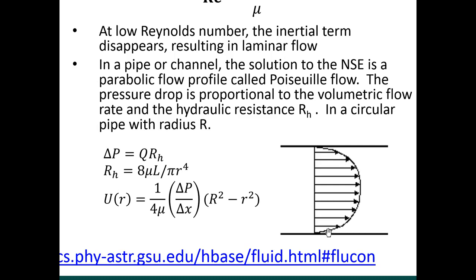All right. Now, this is one thing that is different from the electrical domain. Those of us coming from electrical engineering, when analyzing fluid flow in a pipe, have to consider that we have a velocity profile in there. This has to do with what I just mentioned about the shear stress in the walls of the pipe. Imagine we just have a pipe like this, and we're flowing fluid through there. Near the walls, the velocity of the fluid is going to be 0 because of that no-slip boundary condition. So it's 0 up here, it's 0 down here. The fluid flow is going to reach a maximum in the center of the pipe. You can think of this as sort of intuitive.